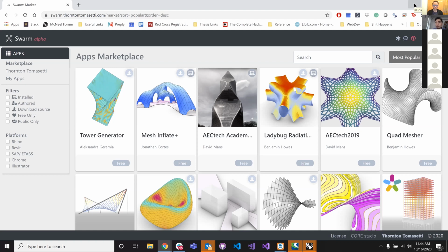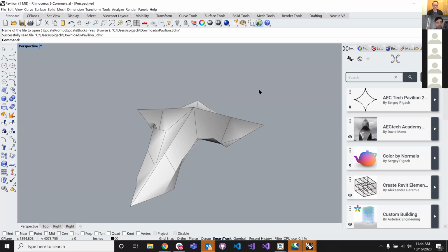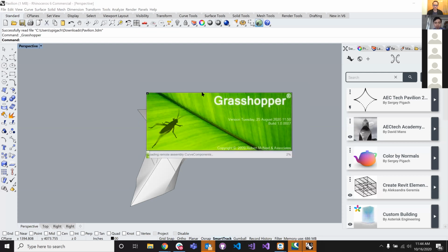Okay, cool. So let's go back to Rhino and open Grasshopper. Hopefully without the rivets, we'll be able to run things a little faster. Yeah, maybe you just disable that whole rivet group to decrease computation time. Yeah, let's do exactly that. And hopefully we'll be able to see this solving live as well.